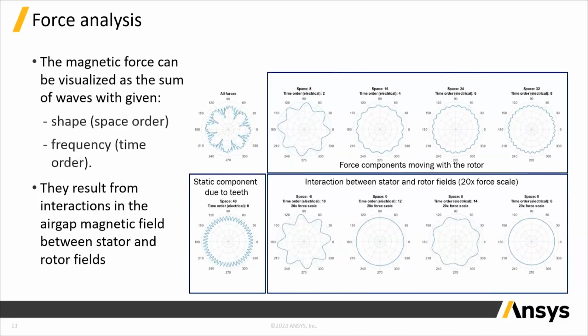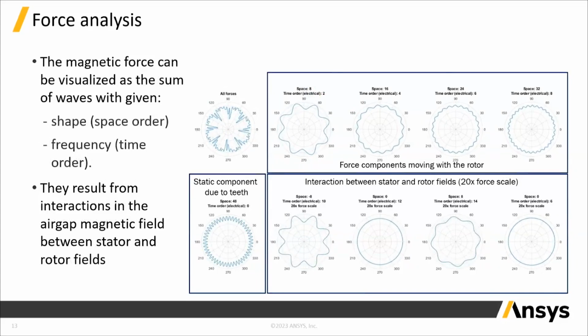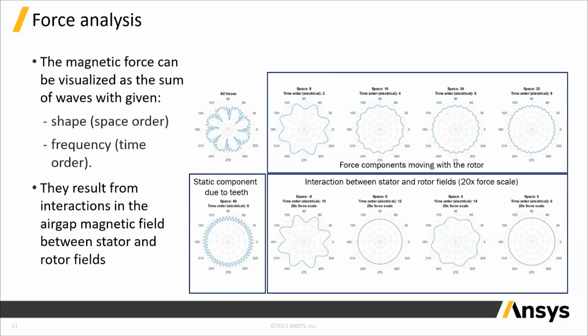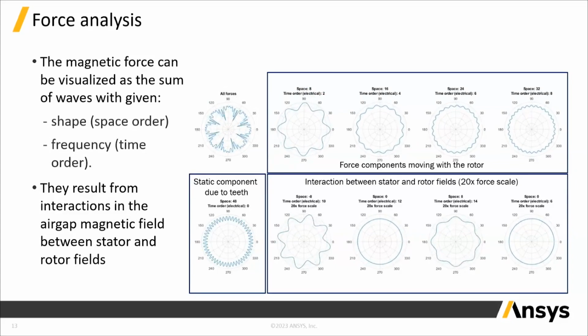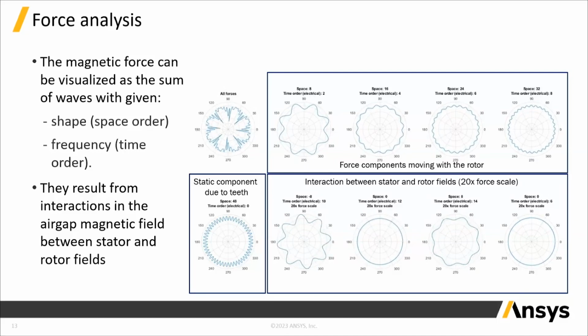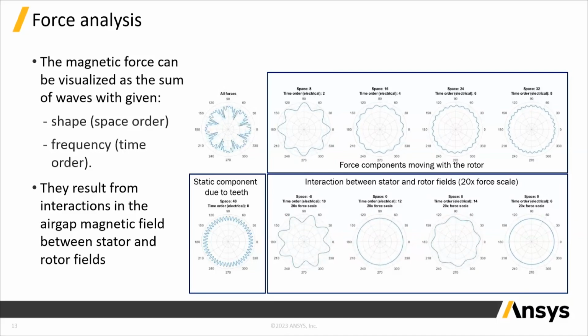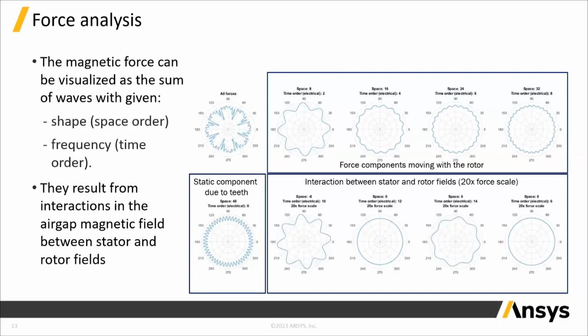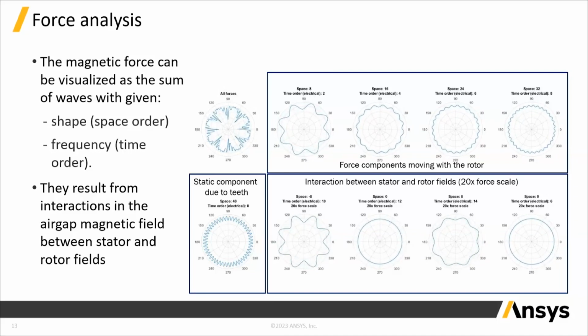In a simple example, if you had a force which is tending to deform the stator into an oval shape, it's much more flexible like that. But for example, here we've got forces which are tending to push the stator into an 8-lobe shape where the stator is much stiffer. Frequency is also very important, both because it defines the sound frequency that will be heard, and it's also relevant for whether or not we get mechanical resonances in the system.